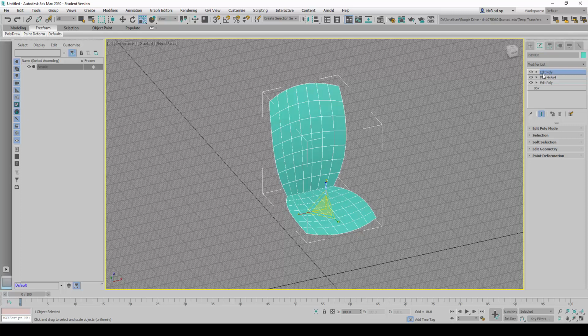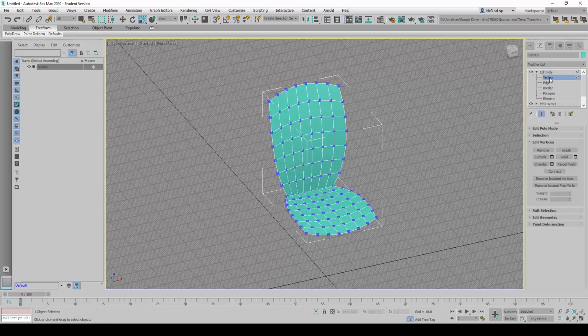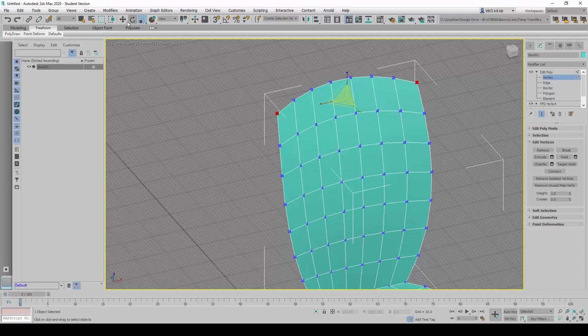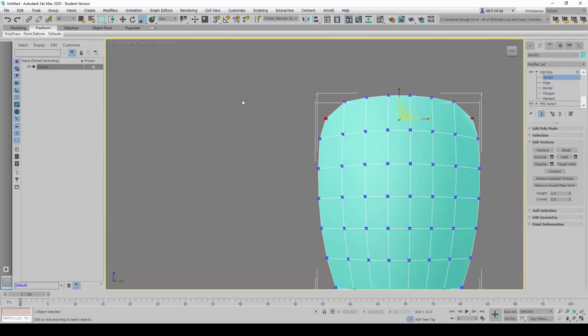And then now we're going to try to activate this by curving it off. There are many ways to achieve the same outcome here. One of the easier ways to do it would be to go to the vertex selection mode here, click on these, and simply shift, move it down a little bit, and then from here do a scale inwards this way, like that. So it creates that illusion of that little curve down here as well.